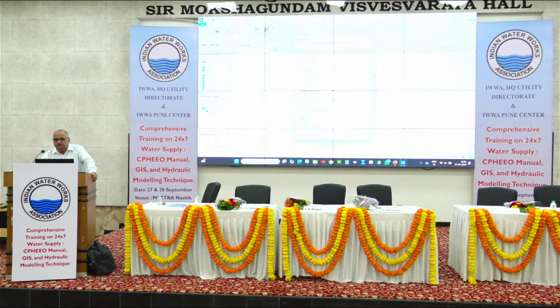Now the data source is this ESRI Shapefile. Why ESRI? ESRI is a company who invented this shapefile. So that's why this prefix is there, they call it ESRI shapefiles. Then elevation data source. Now you have to give the name of your shapefile here. So it is RPN Contour 1 shapefile, which is also there in the backdrop. Now select this elevation field. It is elevation. Our units are meters. So we are giving in meters.